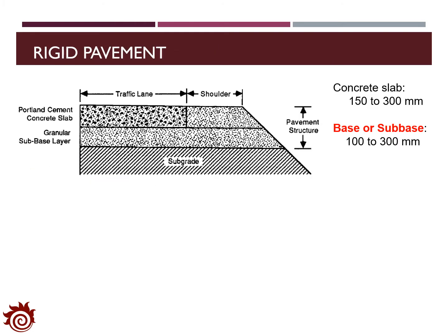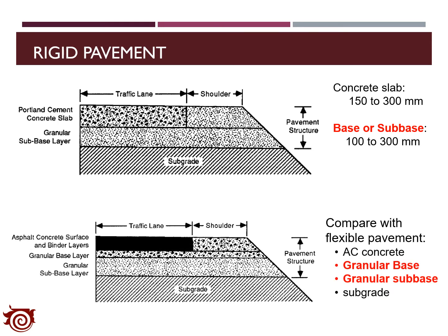The second type of the pavement is rigid pavement, which is generally constructed with Portland cement concrete. In rigid pavement, the load carrying capacity is achieved primarily through the slab action. With this, it can significantly reduce the maximum normal stress reaching the subgrade. Different from the flexible pavement, which utilizes the layered system, the structure of rigid pavement is very simple. It only consists of PCC slab and granular subbase.